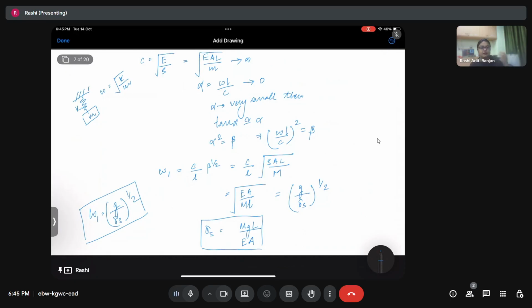So if you relate it, if I use this and k is EA by L, we get omega as under root of k, which is EA by L into M, right? This is what we got for that question that we did in, I guess, live session 1 or 2, right? This is something related to that. You can see over here that the expression is also the same.